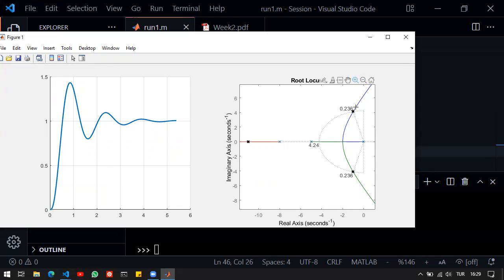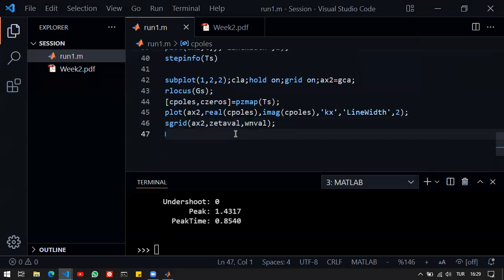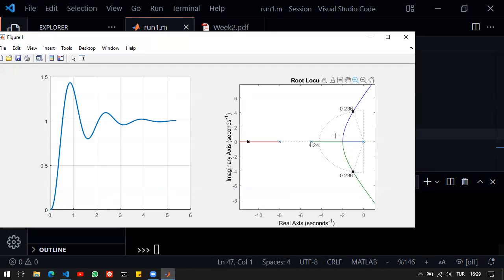And my choice here was to have the multiplication equal to 1. So I was looking for a circle that is basically growing with omega n. And I had a certain zeta value that would change the angle of it. And the intersection is the exact point that I'm looking for. Now, of course, I was not directly choosing zeta, nor omega n, but I've chosen the multiplication of it. So maybe we can also draw a line that represents all the points